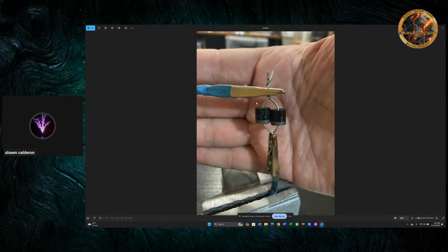Step one, there are 2 diodes on the input. So the variac comes from the bottom up through these diodes and then to the ZVS circuit. These diodes are notorious for shorting out. In fact, believe it or not, the hottest component on the ZVS is not the MOSFETs. It's these little guys here, these little turkeys. I have had so many headaches troubleshooting the ZVS board, only to miss the fact that on the input power from the variac, it's these little culprits right here. So suspect your input diodes first.